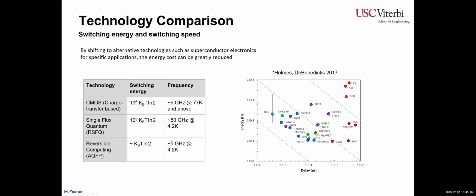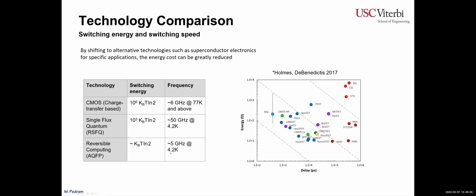And the performance is quite acceptable, right? Even at that, for the HUFP, we are at 5 gigahertz at 4.2 Kelvin. The big problem, the elephant in the room, is that you have to cool down to 4.2 Kelvin from room temperature. And that means maybe a factor of 1,000 loss in energy efficiency itself. 500, I think the Carnot cycle efficiency is about 100 or so, 100 some. But effectively, 500 would be quite good, and more realistically, probably 1,000 at the present time. In spite of that, this is still a good win.